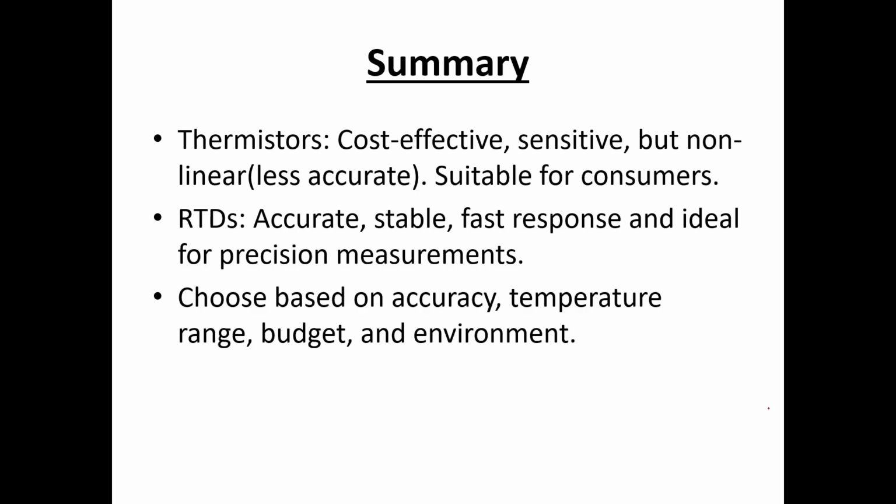In a nutshell, thermistor is cost effective and sensitive, but non-linear, meaning that it is less accurate, suitable for consumers. RTDs are accurate, stable, and ideal for precision measurements. So you want to use thermistors or RTDs based on accuracy, the temperature range that you want, the budget, and the environment. Thank you very much.